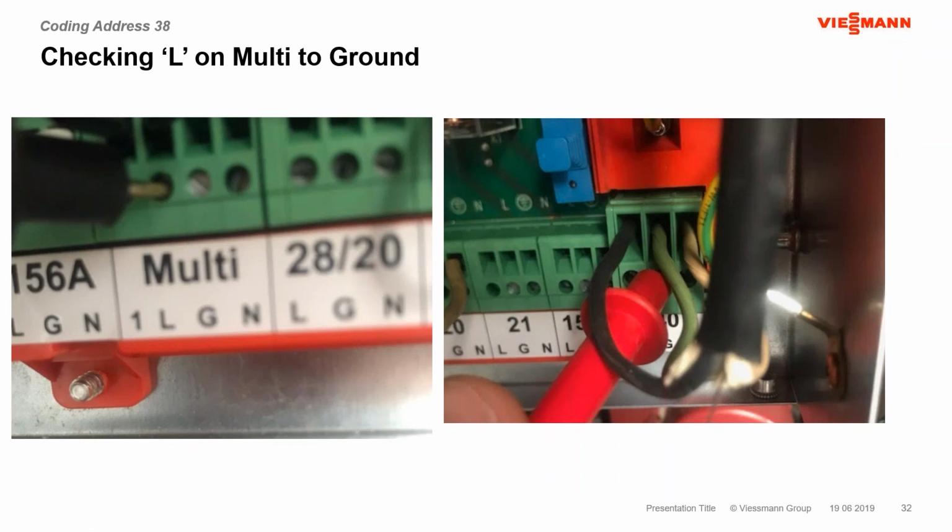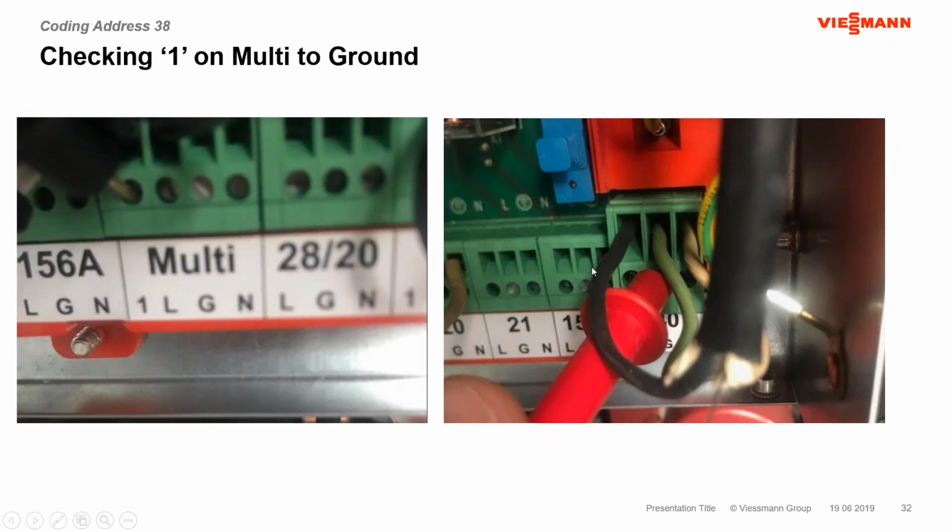We're going to take our meter out, and we're going to start basically looking at where that power is being interrupted. So we can have a look first here. This is my meter. I've got one side on the ground on the 40 plug, and the little red lead, and the black lead here is on the L. I would get 120 volt here, but when I measure between the ground and 1, there is 0 voltage here. So that would indicate that that safety has been interrupted, and we need to correct that problem and move on. So the safety is doing its job. It blocked the burner from operation, and now we need to figure out why that safety was interrupted and fix that problem, hit the reset switch, and now our burner will be in operation.